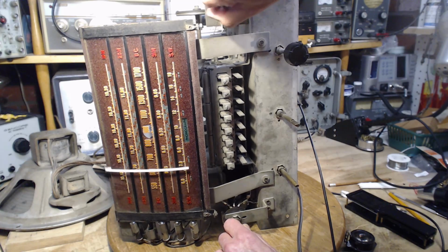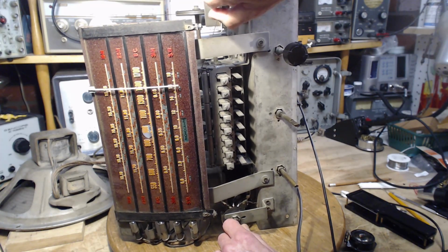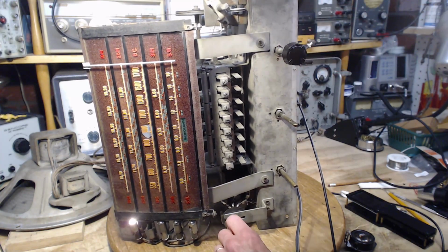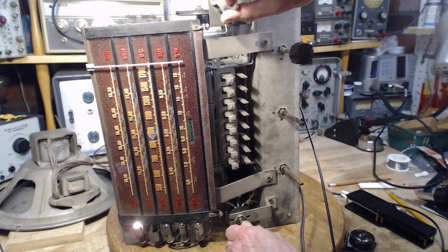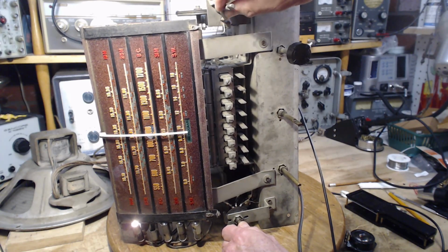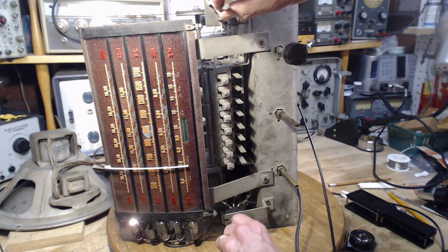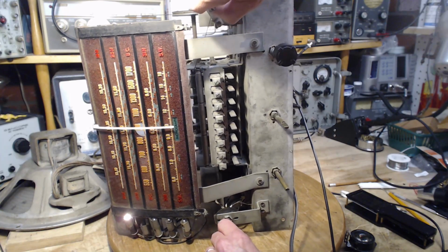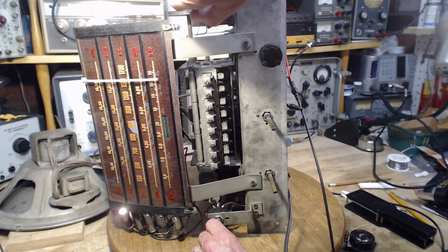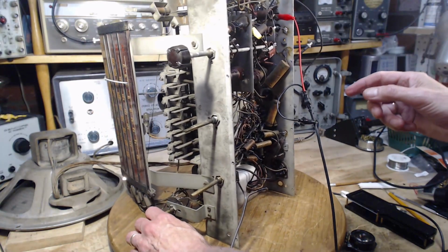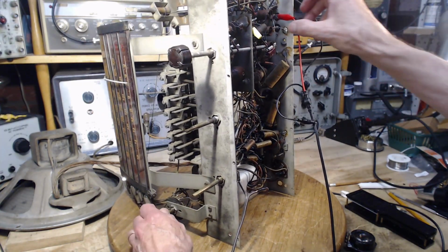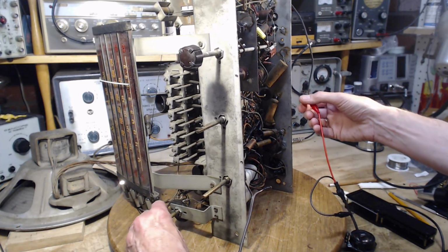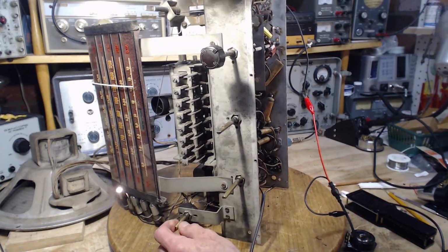Really would expect to pick stuff up here. Last band. 15 megahertz. Well, we're way ahead of where we were, that's for sure. Now, didn't I find that this capacitor back here was nulling out the antenna a bit? Let me bypass it. Just go on this wire here. It's definitely more antenna signal.